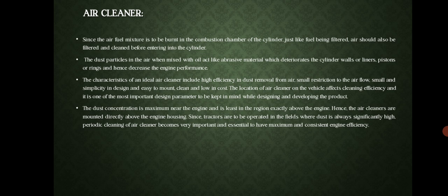The characteristics of an ideal air cleaner include high efficiency in dust removal from air, small restriction to the airflow, small size and simplicity in design, and being easy to mount, easy to clean, and low in cost. The location of the air cleaner on the vehicle affects cleaning efficiency, and it is one of the most important design parameters to be kept in mind while designing and developing the product.